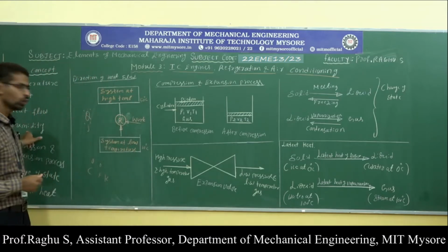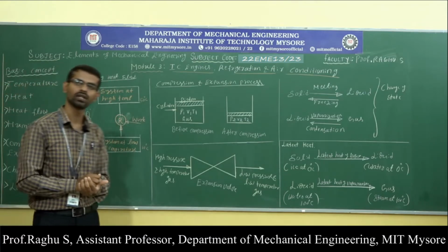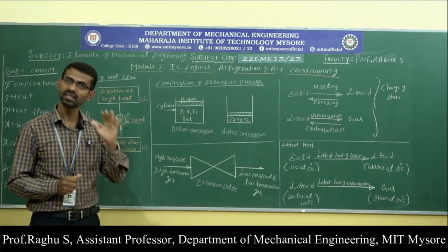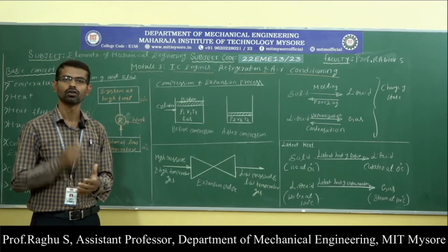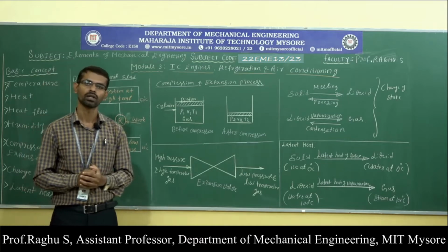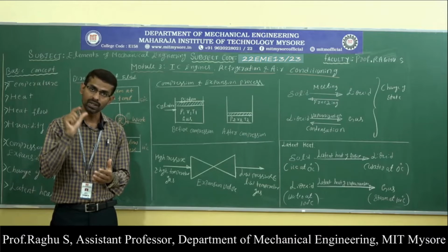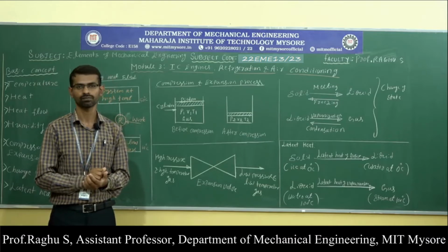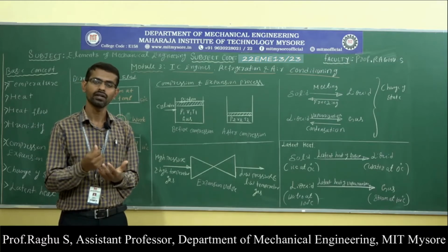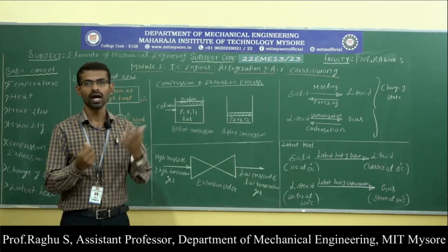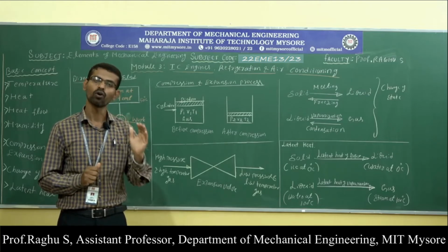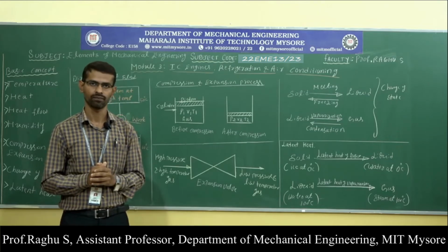Now, humidity. What do you mean by humidity? Humidity is nothing but the amount of moisture content present in the air. The amount of moisture content present in air depends on temperature. Usually warmer air, hot air, can hold more moisture than cold air. That is called humidity.